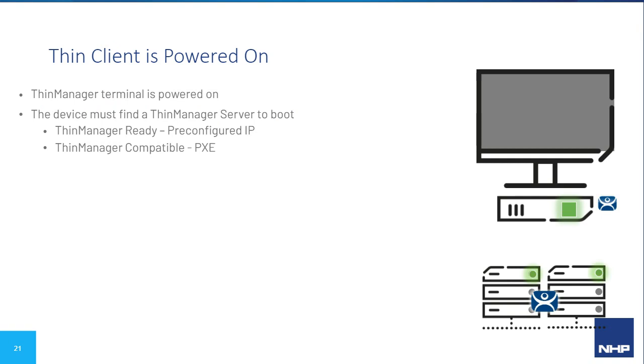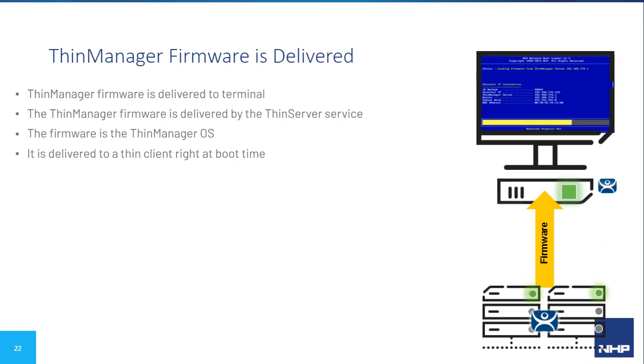If it's what we call a ThinManager Ready device, it has the IP address of a ThinManager server in it, or if it's an off-the-shelf open market device, it will boot using a standard network protocol called PXE. Regardless, the ThinManager server must be running and the device contacts it.